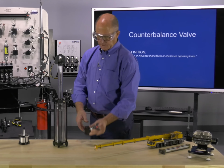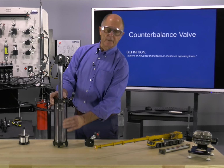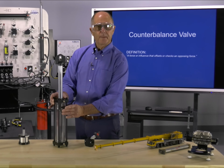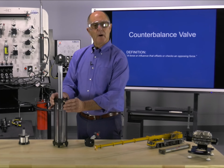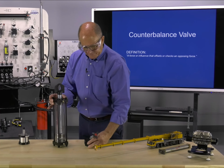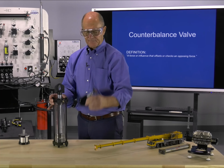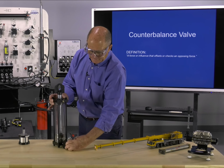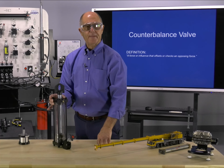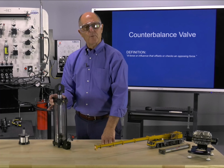In other words, here's a transparent cylinder, and imagine we've got this filled with hydraulic oil, and the line breaks at the bottom. It's going to collapse. However, if I put a resistance in the form of a valve in the line directly at the cylinder port, I can prevent that from happening. That's the valve we're going to talk about today.